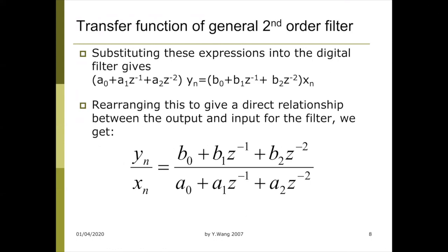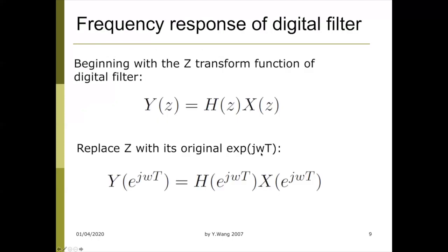All right, so what is this Z indeed? How can we, from the Z transform, judge whether this filter is low pass or high pass? That is what most people are concerned about, because mathematically Z is not equal to frequency, but it has frequency information encoded there. So mathematically, Z is equal to, I have this e^(jωT) here.